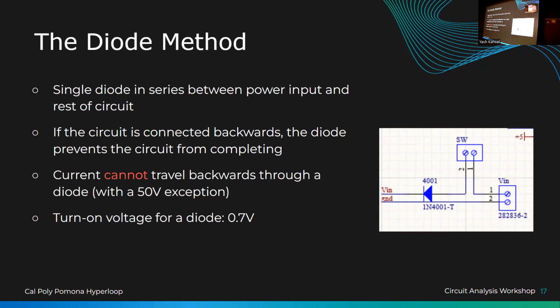Also important is that the diode is not perfect. It has the arrow, but it costs you a little bit of voltage. It says for you to go by, you have to give it 0.6 volts, typically. So it does have a voltage drop going from one side to the other through a diode. Also, LEDs are a form of diode.